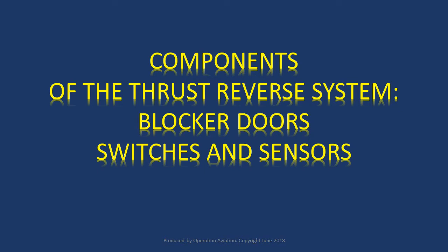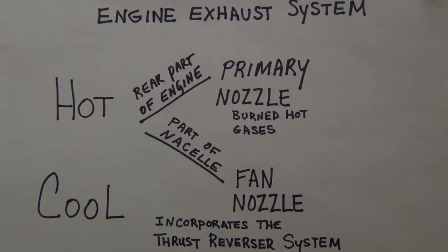Of course, you have latches, and if you're doing maintenance and you latch them, be very careful. Make sure that every single one of them is latched securely. Even though everything locks in place, double check that all of them are latched, because under tremendous pressure, namely up at 40,000 feet, that can become a problem, and we don't want a safety issue up at 40,000 feet or on the ground.